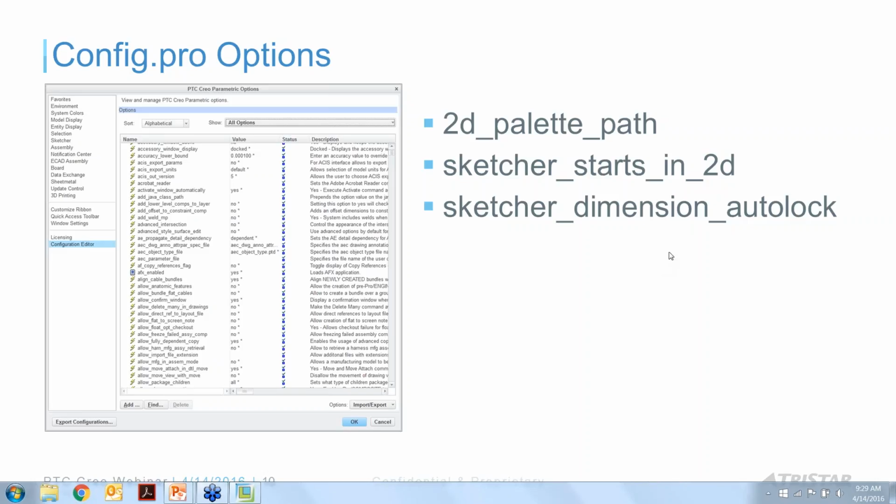However, you can still drag a strong dimension. So that means that I have a line, and if I drag the endpoint of that line, it'll modify that dimension. A locked dimension, what that one will do, it will prevent any dragging from happening. So if it's something that's pretty set, you don't want to modify it by accident, a locked dimension, that's what it will do.